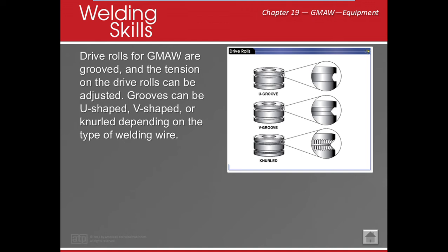It's called a push-pull gun, and it has a little spool inside the gun itself, and it's made for materials like aluminum that tend to slip with traditional drive rollers. So it just pushes it out and pushes and pushes. And that means we don't have very far to go for it to have issues, okay?